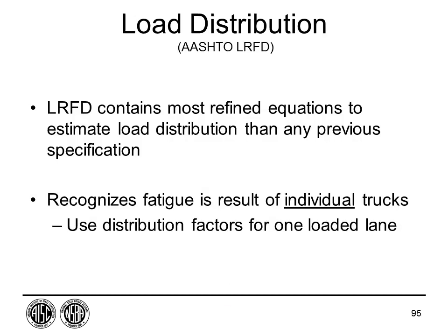What about the load distribution? Well, if you remember in the analysis section, there are distribution factors that are used to get the stresses in the girder and the moments in the girders based on how the loads are applied. Now, the load distribution equations in AASHTO are very good, but if you recall, for strength design, it's basically assuming all lanes are loaded. But we said earlier that fatigue is for individual trucks.